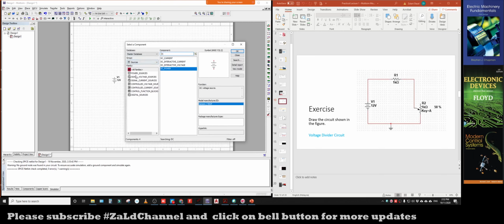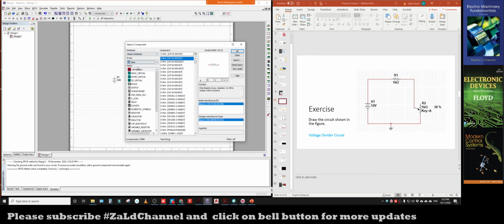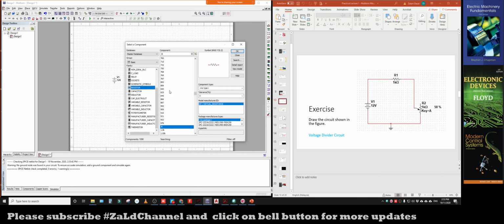So for the resistor component, just search it in the group. The resistor basically belongs to the basic group. All right, so we click on basic group, then we find resistor. Okay, we find resistor is here, right? So click on resistor, and it will appear with different ratings of the resistor.